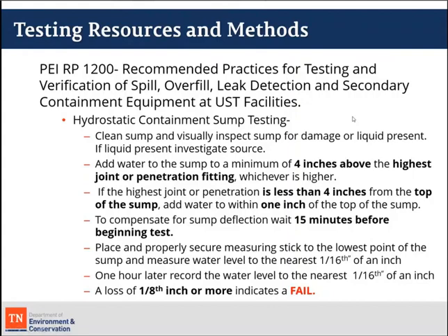You want to compensate for sump deflection, especially if you're putting a lot of water in. So once you get the water to your appropriate level, you'll want to wait 15 minutes to let that sump stabilize, to account for any sump deflection, before you begin your test.